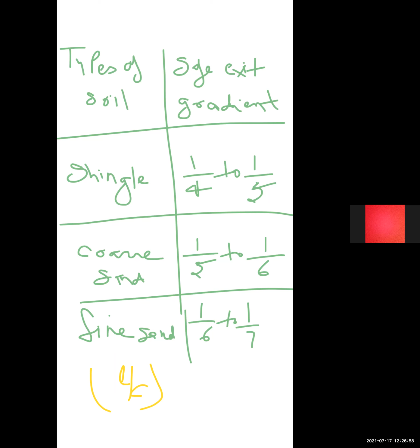So all these modern aspects and other details about designing a weir on permeable foundation as per Khosla theory have been discussed. Khosla theory differs from Bligh's theory in all the above points, but owing to its simplicity, Bligh's theory is still used for the design of small works, that is weirs and barrages, with a minimum practical thickness for the floor, and a deep vertical cutoff at the downstream end.